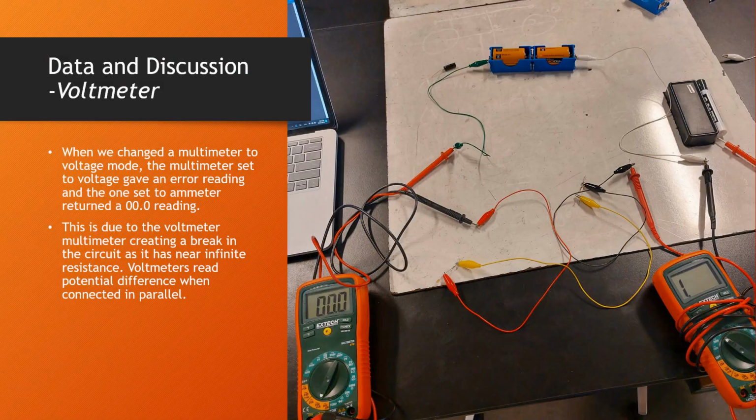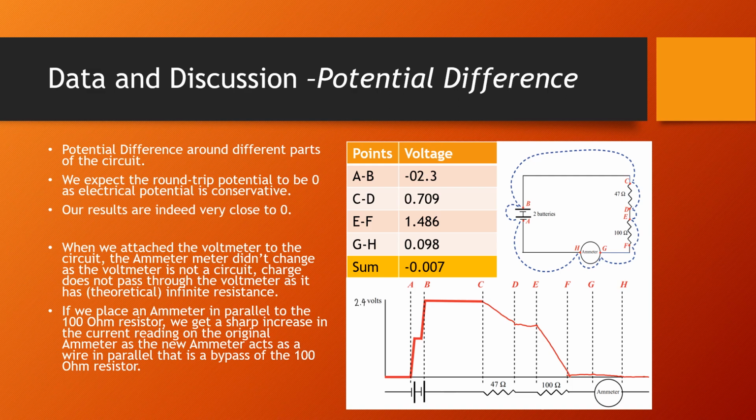If you hook up a voltmeter, when we change a multimeter to voltage mode, the multimeter set to voltage gives us an error reading, and the one still set to current gives a 0 amp reading. This is because the multimeter is essentially a break in the circuit. It technically has really high resistance and theoretically has infinite resistance if we're going for an ideal voltmeter. And this is because they read potential difference, and there wouldn't be a meaningful potential difference if there were no resistance.